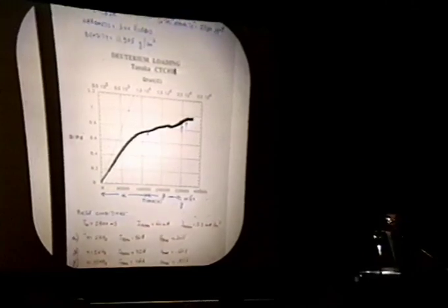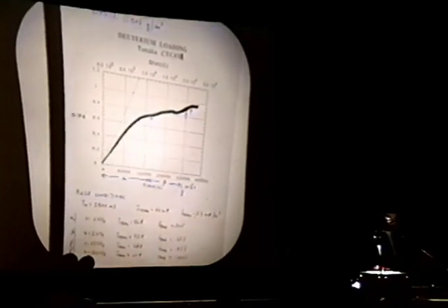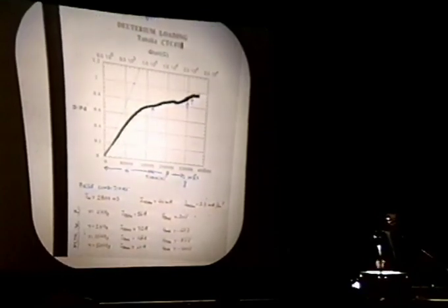After that, we look at what happened. It seems that after 2 days, more or less, the palladium reached a stable value of 0.65, the conventional beta phase. So we try something to increase the palladium ratio. We increase the peak current and reduce the frequency. After that we wait again and we see another stable phase.